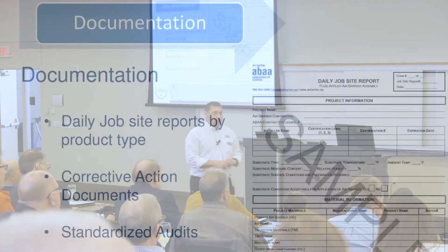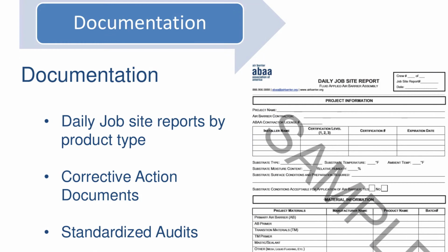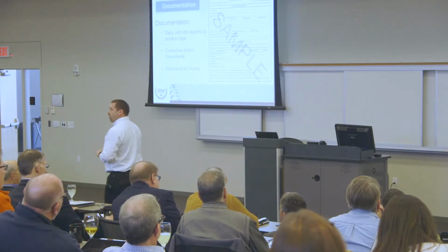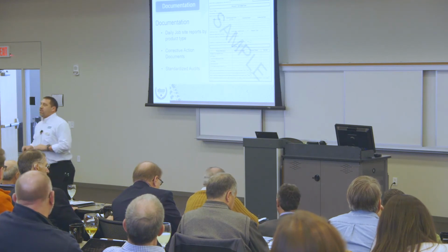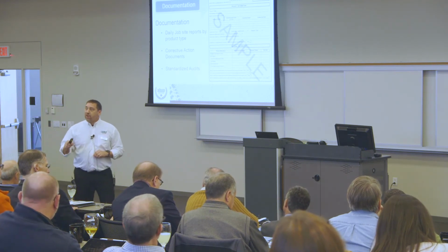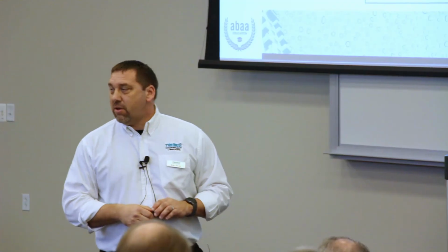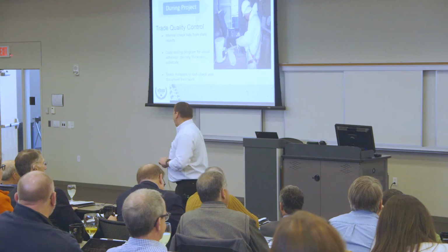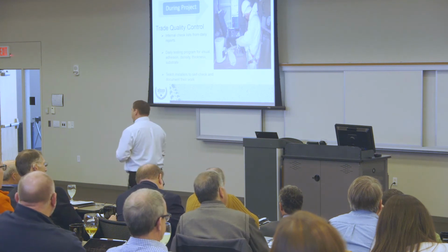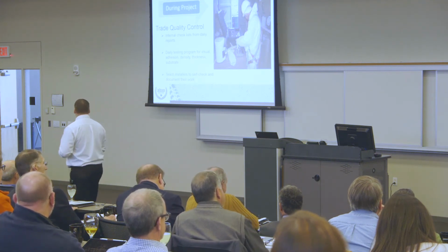Documentation. Those installers have to fill out dailies. They have to do it. The auditors come out and check that. We're going to talk about auditors in a second. If they're not filling out their dailies, they're not doing what they're supposed to do, they can lose their accreditation and their certification. There's some teeth to the program. Quality control, again, this is doing the spray foam density test. It needs to be done. That's part of the dailies if you're doing spray foam. These guys have to do it.